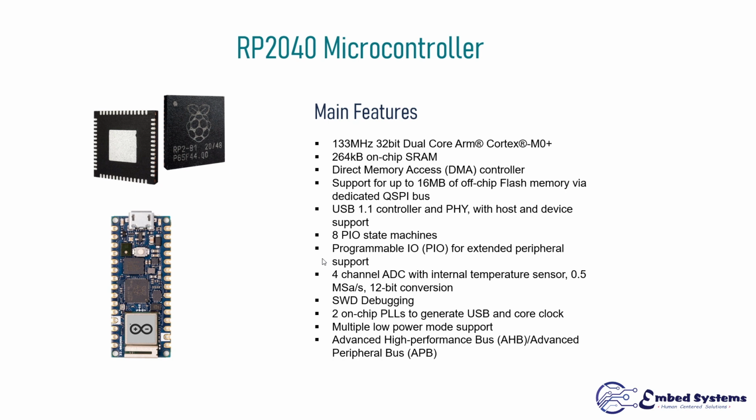It's an RP2040 microcontroller. This microcontroller is the one used in an Arduino RP2040 Connect. It's based on an ARM Cortex M0 microcontroller. It has good features actually. It has some 264 kilobytes of SRAM. It has a DMA controller. It has several input-output pins for various sensors.